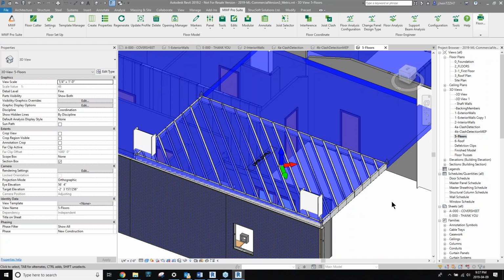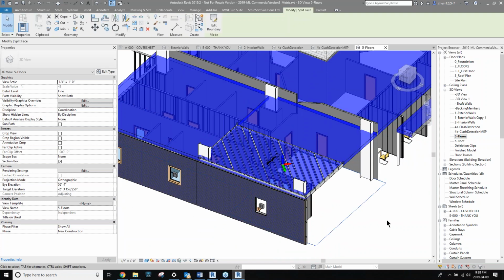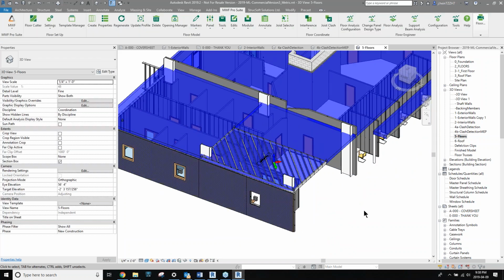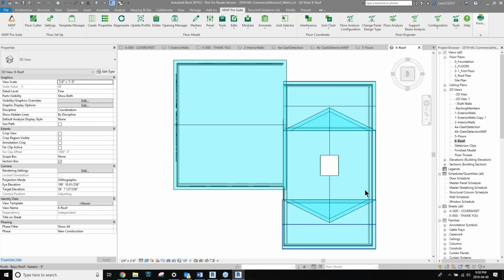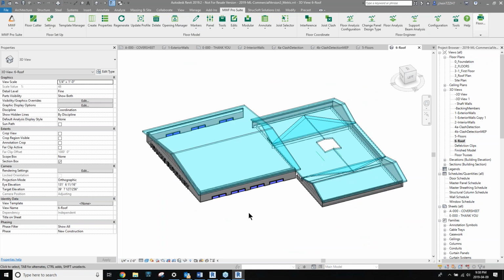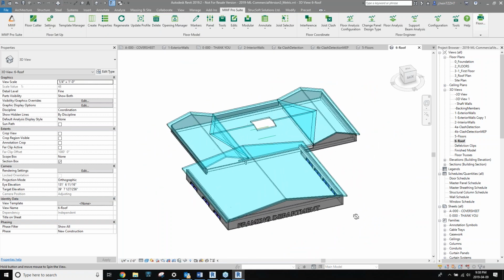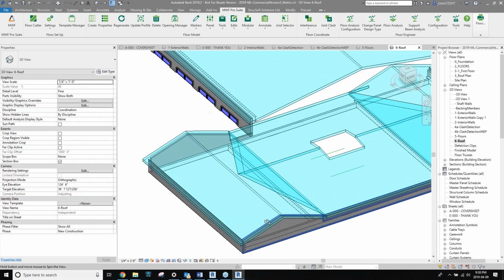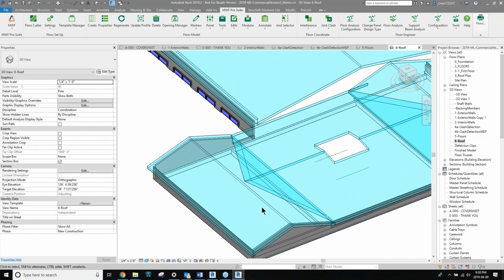I know I'm missing one family to be able to do it. I'm missing my cutter. I could drop it on, but it would put your sheathing on and lay it out accordingly. So floors act very similar to the walls. In the roofs, we do have some trusses that we can do for you. In the advanced metal software, we can engineer a truss for you. In the Pro Metal, we just give you the profile with no engineering so that you can give it to an engineer.